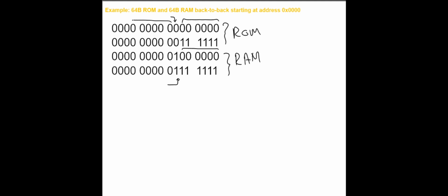So for example, we have a system that has 16 address bits, and only the lowest 7 bits are being used to access locations in the memory, whereas out of these 7 bits, 6 of them are going to give me a location in the memory type, and then the 7th bit is going to select whether that location is coming from the ROM or from the RAM.